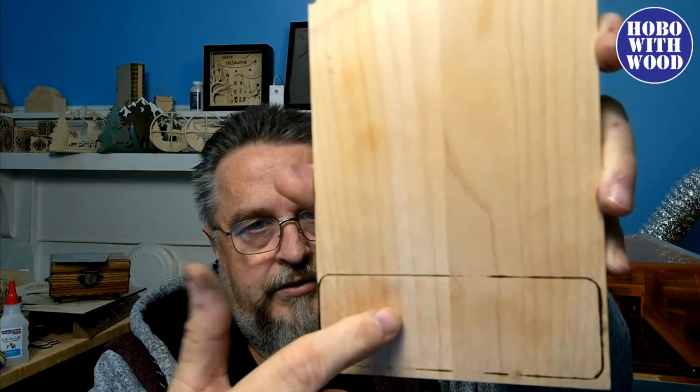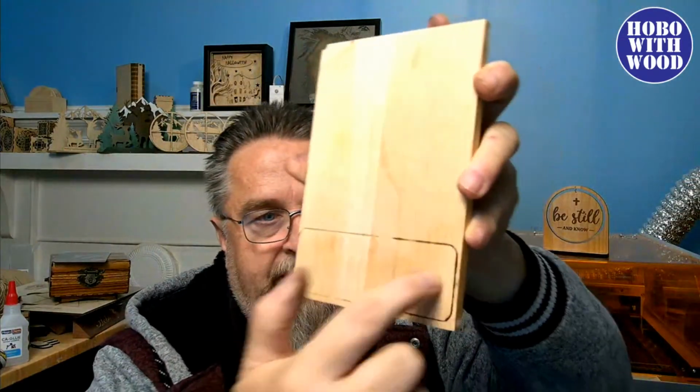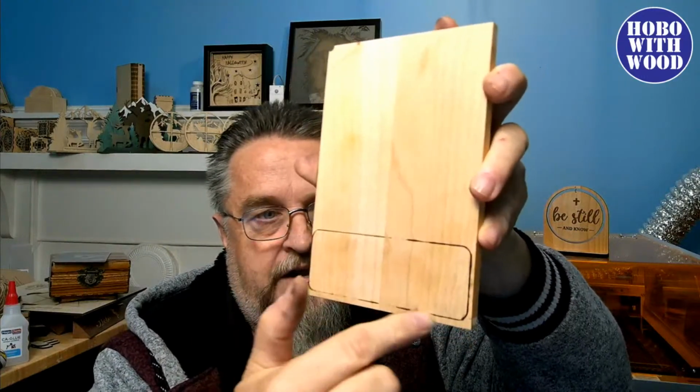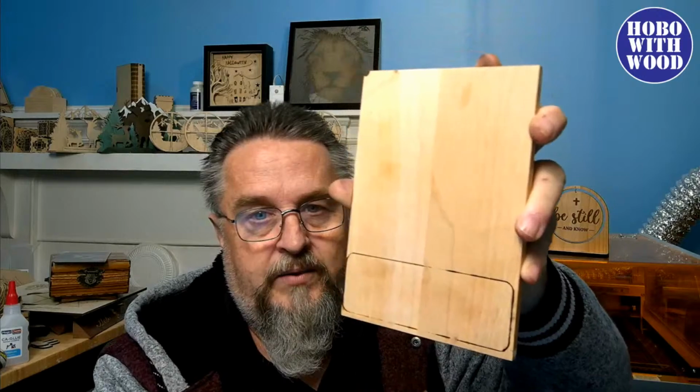This side cut through with 7 passes at 10 watts, 100% power, at 420 millimeters a minute. It cut completely through. This side had no evidence of a cut on it at all. It was perfectly split where those two pieces of wood went together.